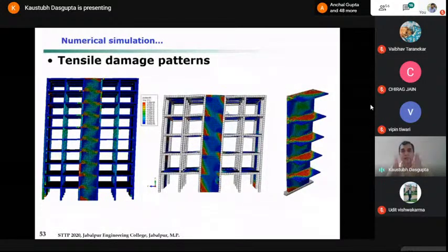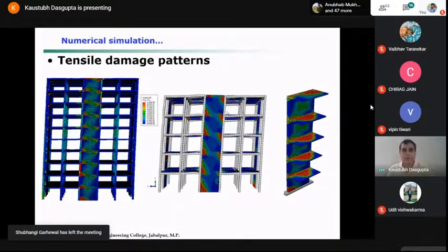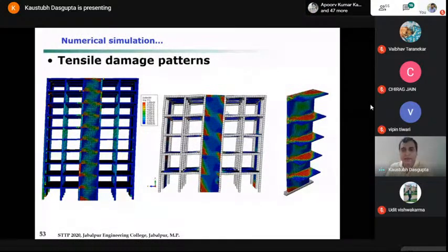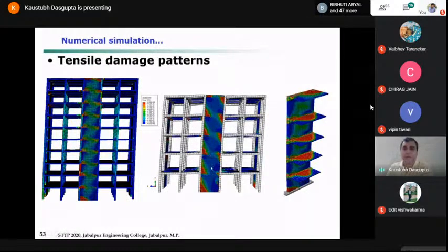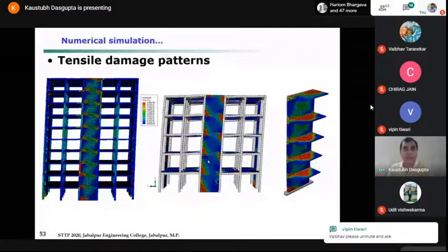Unlike your isolated standalone cantilever type of behavior, where you have continuous regions of tensile and compressive stresses, you are getting repetition of certain stress distribution. So, in other words, your basic behavior of the slender wall as a standalone isolated cantilever wall is not holding good when it is connected to floor slabs.